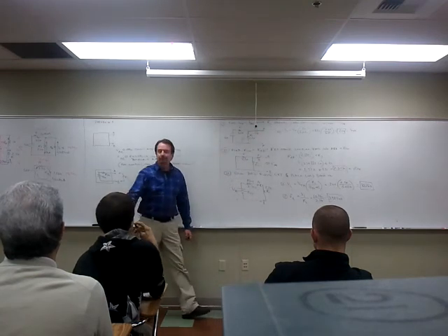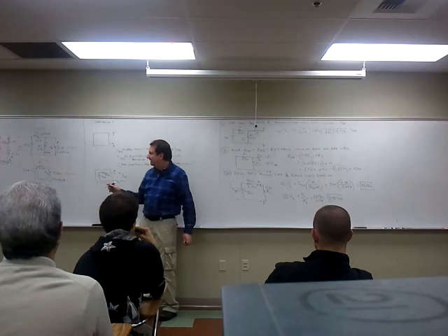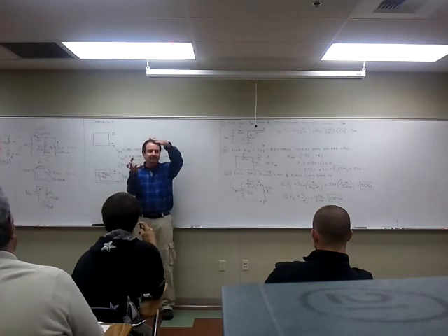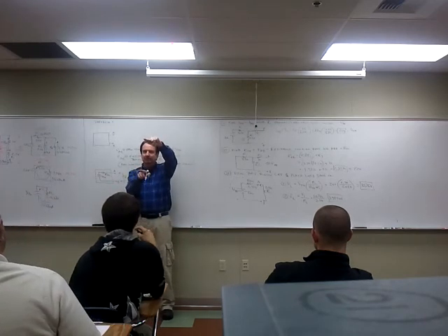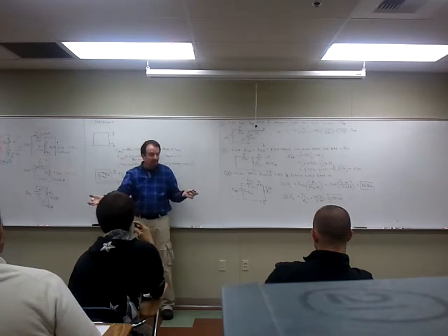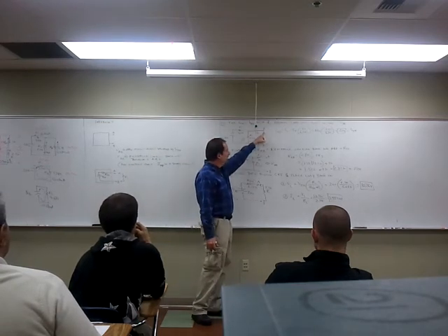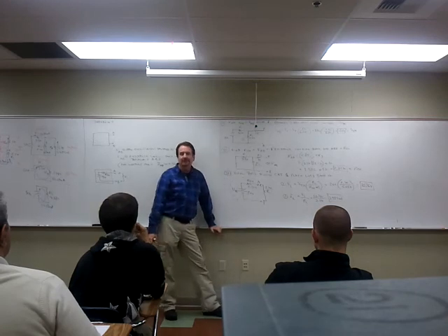So you remove the load. The first step in Thevenin's is if the load is not already removed, you remove it. Now, sometimes you're Thevenizing where it's something driving something, the terminal is just hanging out there, and you haven't even put a load on it yet, and you're making the Thevenin equivalent. So, in other words, the load could already be gone. In this case, I removed RL. I want to find the open circuit output voltage.